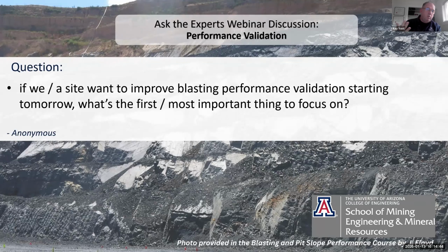Yeah. One more comment, which relates to the cutbacks and things like that. You need to get this all sorted out while you're on intermediate pushbacks, because if you're already mining your final limit, if you do end up with any geotech step outs and slope angle reductions because you're not achieving your design acceptance criteria, you've got no comeback.